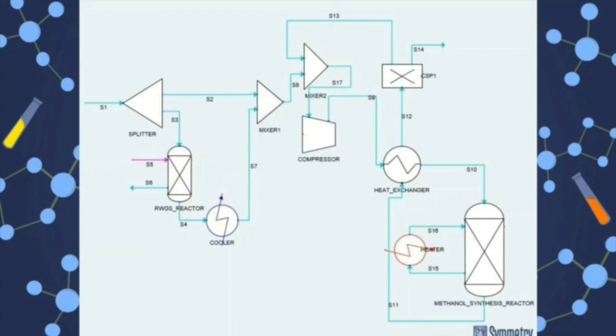As we have shown in the diagram, reactor walls are coated by the membrane. Water penetrates through the membrane layer during the reaction. A sweep gas, nitrogen, flows in the permeation side to carry the permeated H2O. CO2 and H2 are partially converted to CO and H2O by the RWGS reaction in an adiabatic reactor.